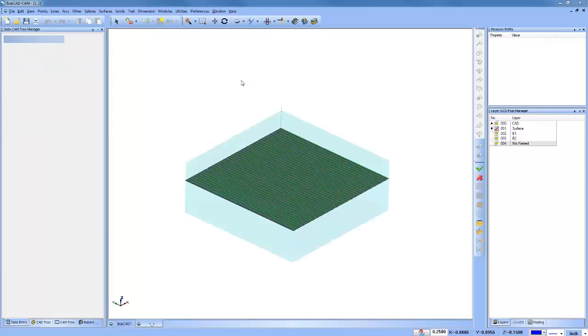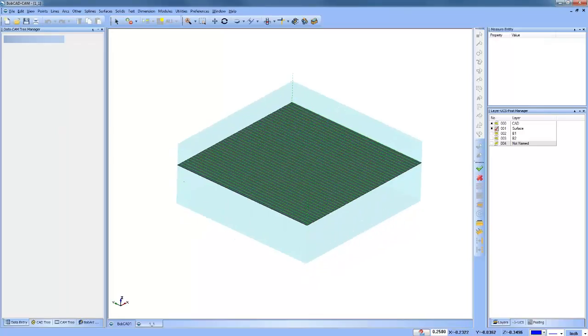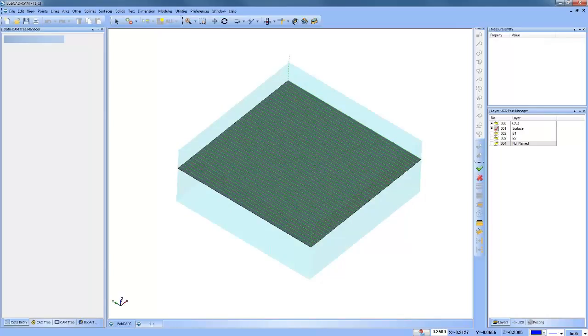So the first topic we're going to talk about is going to be trim and relink. Trim and relink is a command used to trim your selected toolpath to a boundary, allowing you to remove unwanted toolpaths. So I'm going to start with a very simple example. Now, in the previous webinar, I covered mainly 2D machining. In this webinar, I'm going to get into more of the 3D machining.